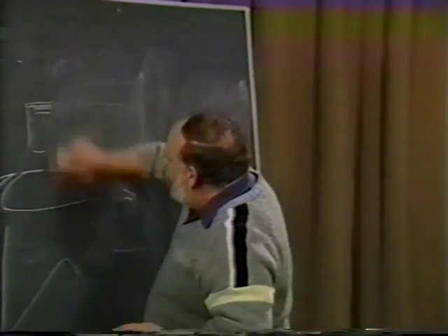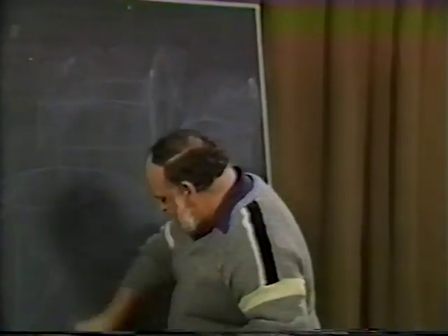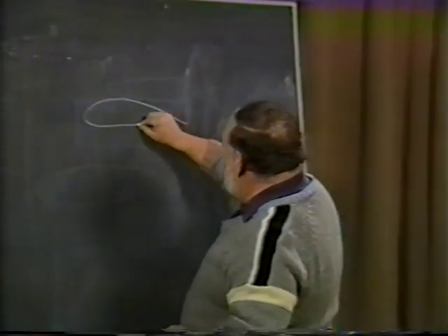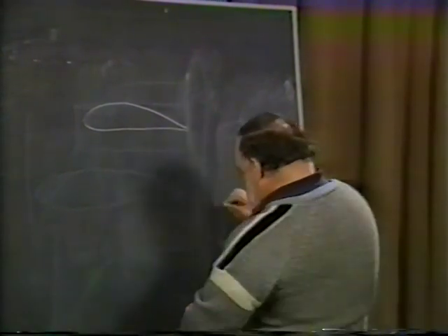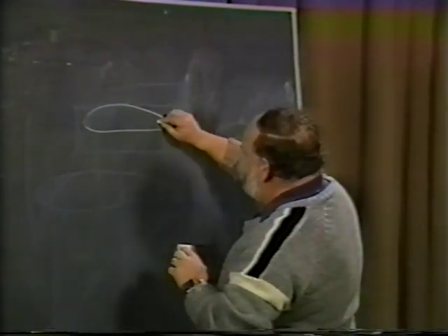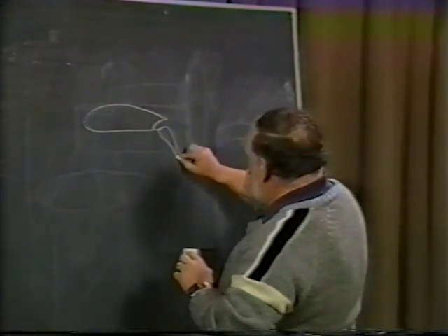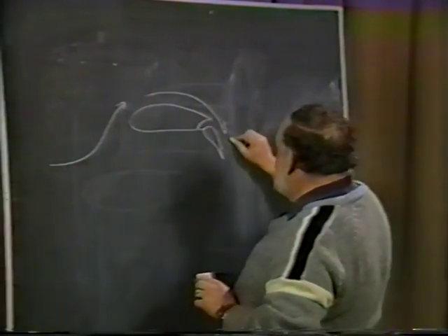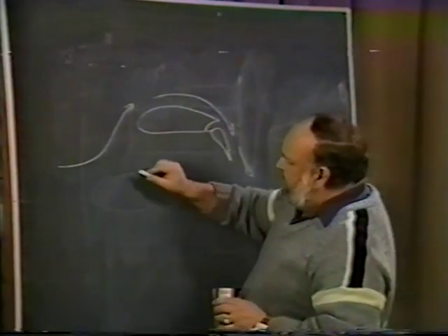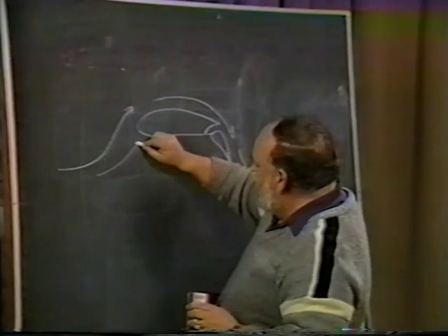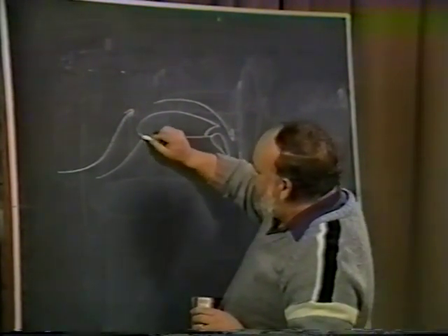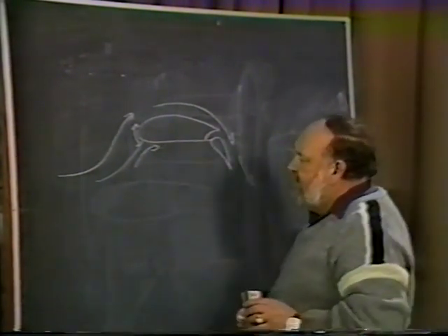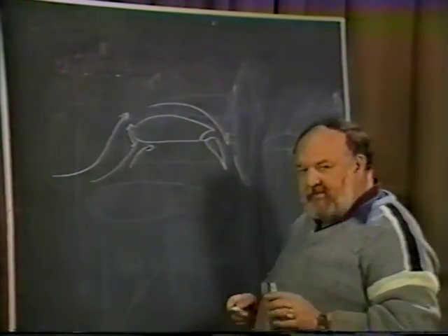And one of the things they found that occurred that was sort of strange was that if you have your wing like this, and if you have really good, powerful flaps built into it, to where you will be pulling in a great deal of air over the wing and producing real high CLs, your stagnation point, the point where the air comes along and hits the wing, and on one side of this point the air goes around the leading edge, and in the other case, it goes under the wing, where this stagnation point is something you have to be aware of.